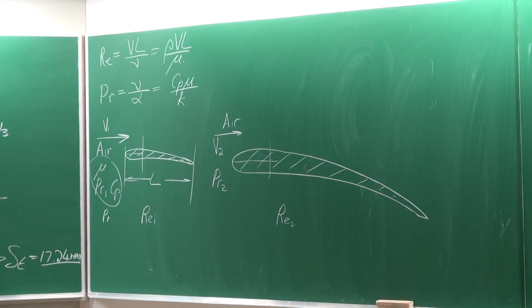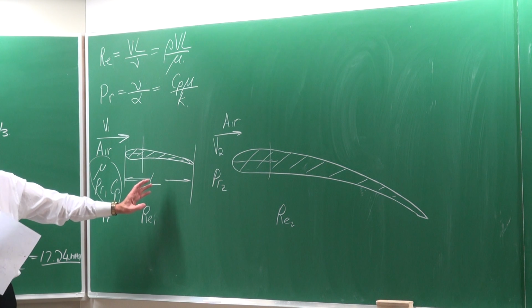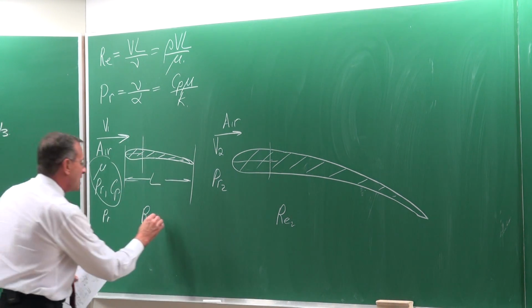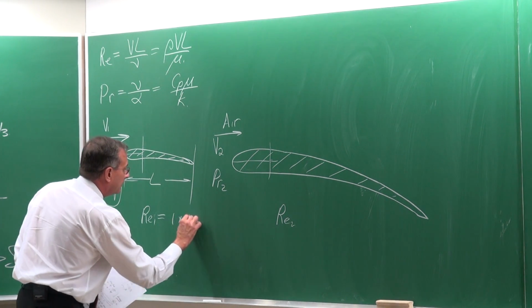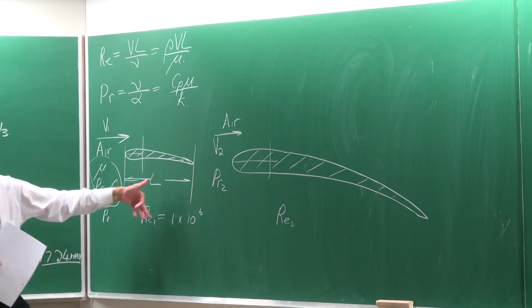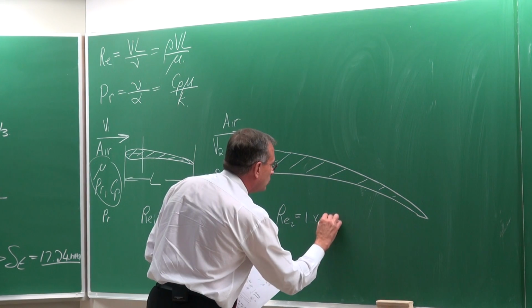And you know that from fluid mechanics. It therefore means that we can do experiments in the wind tunnel, and we can take drag measurements. Now let's suppose this Reynolds number is equal to 1 million. Then we can use these results for the case where that Reynolds number is also equal to 1 million.